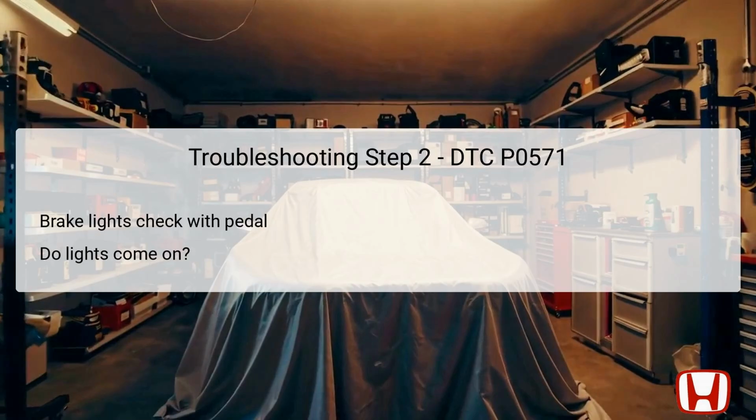In the second troubleshooting step, the inspection continues by checking the brake lights with the brake pedal pressed. This test is critical because it assesses whether the brake pedal position switch is functioning correctly when engaged. If the brake lights illuminate as expected, this suggests that the switch is potentially operating correctly in that position.